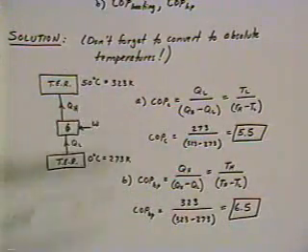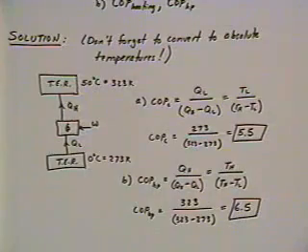Now, notice that in the case of efficiencies, you're only getting answers that are between 0 and 1. The Carnot efficiency, of course, for a heat engine or for a power plant is the maximum efficiency that you can achieve, and in real life you're not going to get that much. But coefficient of performances here are numbers that are greater than 1, and so that's good.